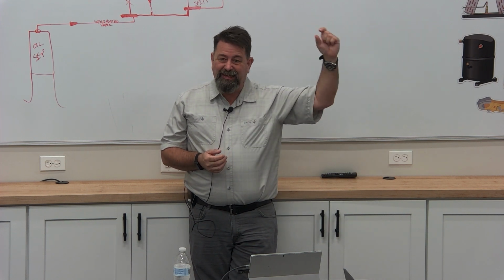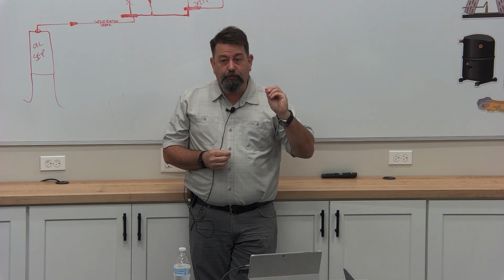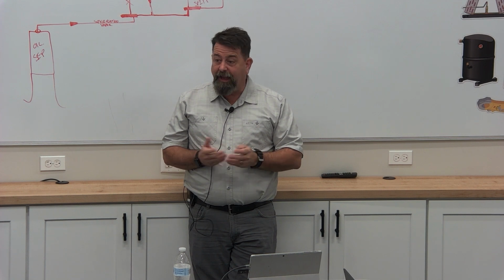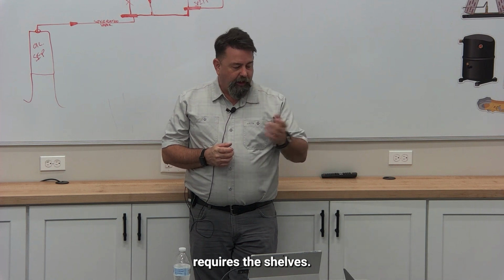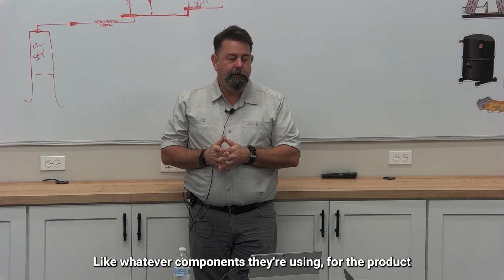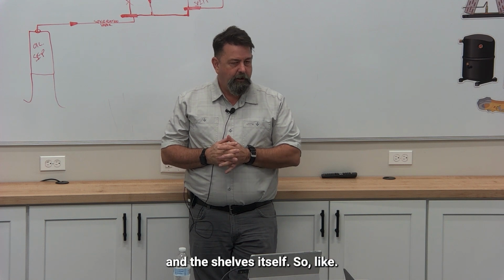My final case temperature EPR, right? I can't do anything on those final settings until my shelves are in place. I'm guessing on what it's going to do. And it doesn't require product in the case to do that, it just requires the shelves. Correct. Whatever components they're using for the product and the shelves itself.